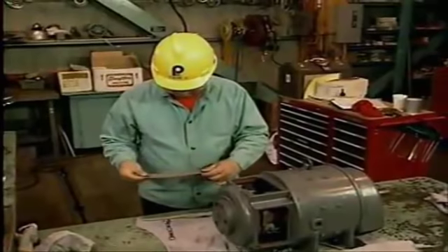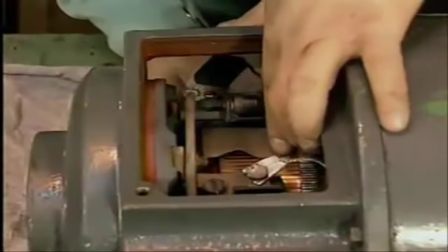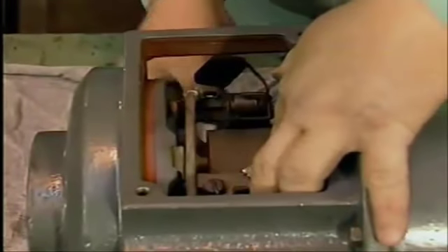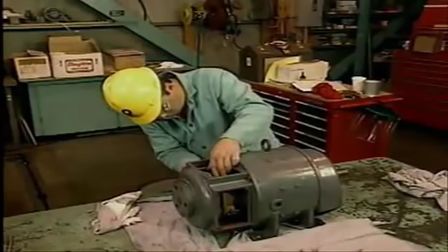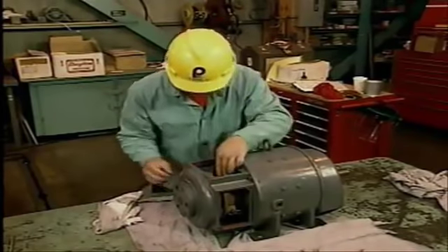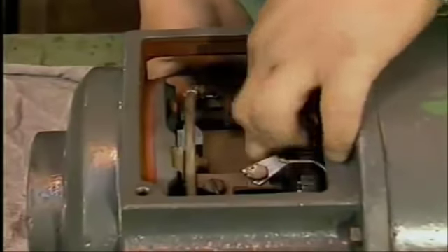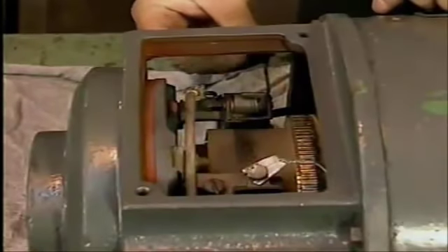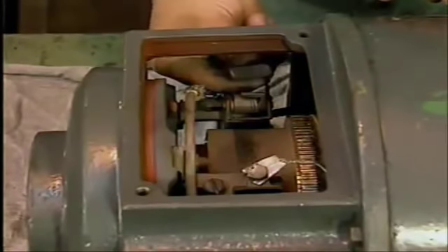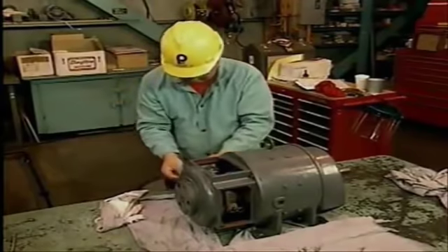When this method is used, a strip of flint paper is torn off that is at least as wide as the brush. The strip of flint paper is then placed on the commutator with the flint side out. The brush is placed in the brush holder, and the tensioning device is adjusted to hold the brush tightly against the flint paper. In this example, the motor's armature is then turned slowly back and forth a few times. The brush is then removed and inspected to see if it has the same shape as the surface of the commutator. If it doesn't, the procedure with the flint paper is repeated. When the shape of all of the brushes conform to the shape of the commutator, the seating procedure is complete.